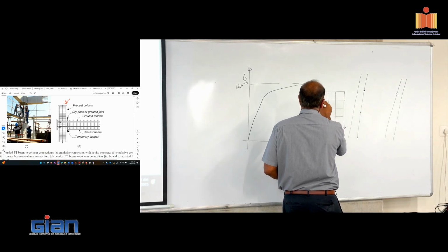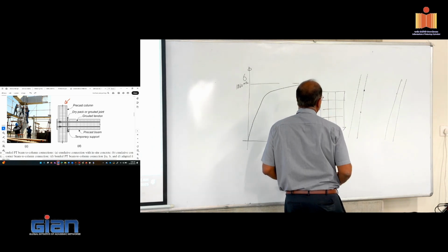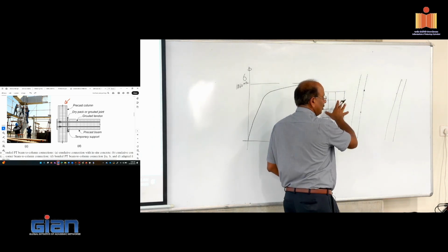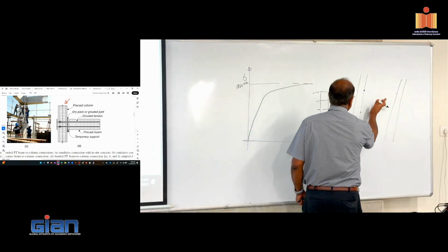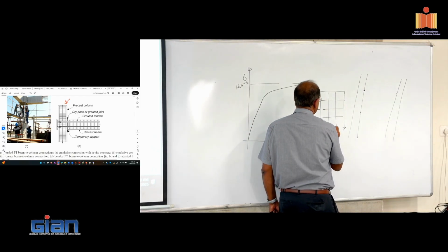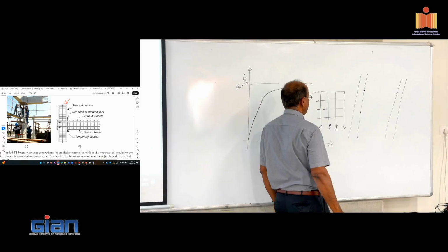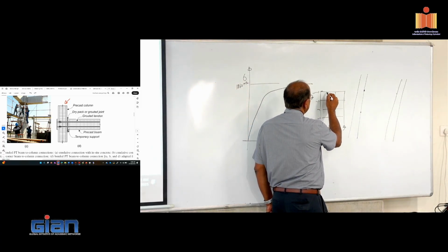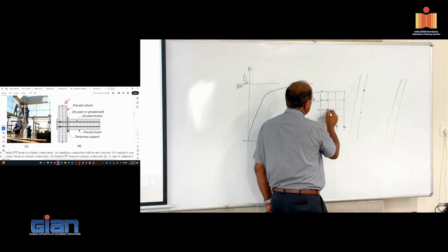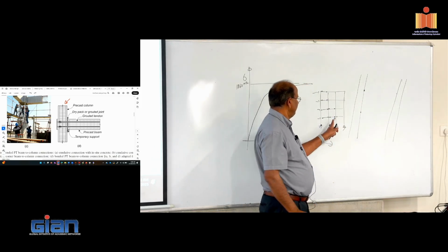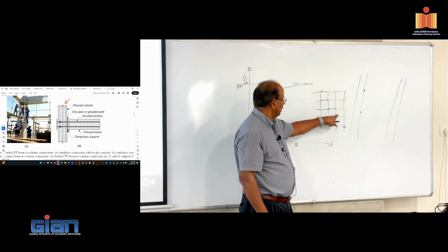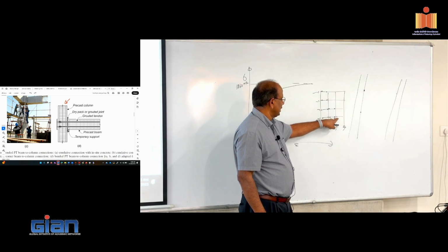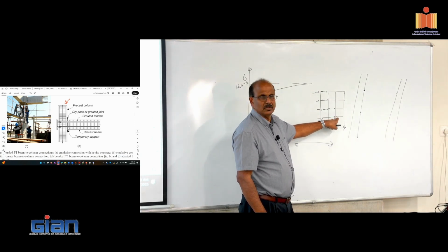So if you push on it, I think Professor Amalan talked about equivalent static load this morning. You're pushing it, so the building is going to start swaying. All of these regions will develop plastic hinges. In order to distribute the plastification, you will allow the plastification to take place at all of these regions. And you do that by making this location weaker than the yield moment capacity in the column, so that you force this to yield.